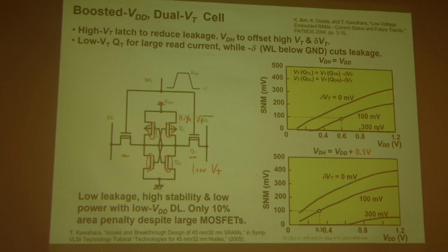So that means your word line voltage may not be the same as your power supply VDD here. You can use different voltages to engineer your SRAM cell for certain applications, right? If you want to read faster or write faster, depends on your targets. You can engineer this. There are many design tricks.